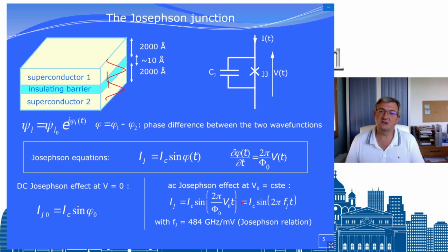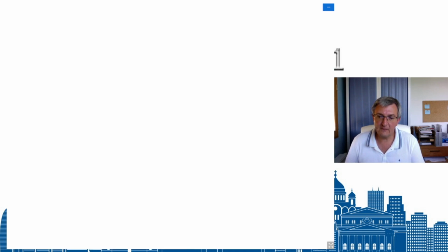So this is a DC voltage standard. You can find the DC voltage accurately. You can measure it and you can calibrate it accurately. There are also AC standards which are developed on Josephson junctions. It's current development, I would say, and I will not talk about it because I cannot talk about everything. There are a lot of things, but today the work is based on using the same Josephson junction in different modes to do also AC standards, meaning you are able to fabricate in a quantum way a sinusoidal AC signal of a few kilohertz or megahertz, and then you can use it as a reference.